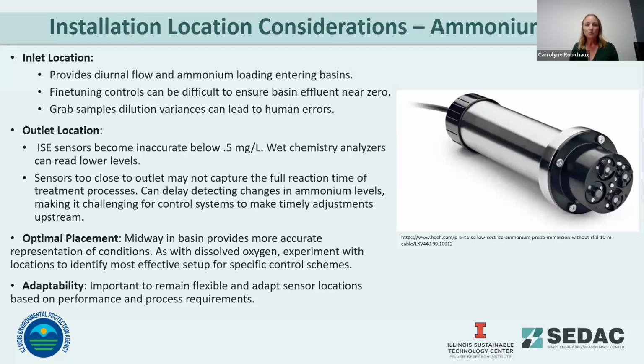I don't believe I wrote it in one of these slides, so I just want to talk real quick about that control schematic. If you have one sensor, say a dissolved oxygen sensor, what happens when it becomes very dirty is it actually starts reading down to 0 ppm. If you are automatically controlling your blowers based off of that DO or ISC measurement, and you have one sensor that fails, your blower is going to ramp all the way up.